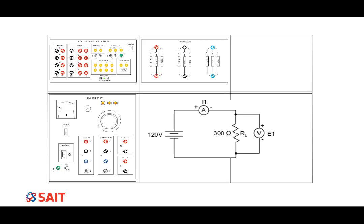Once the schematic is designed, a wiring diagram can be created before constructing the circuit. Always build your circuit from a wiring diagram. In large circuits, sometimes you may find it easier to draw the wiring diagram if you highlight or mark the parts of the schematic that you have completed. To start, I'm going to draw the wire that is connected from the positive of the DC source to the positive 4 amp input of meter I1. I will highlight this connection and then draw it on my wiring diagram. I will follow the same process for the rest of the connections.